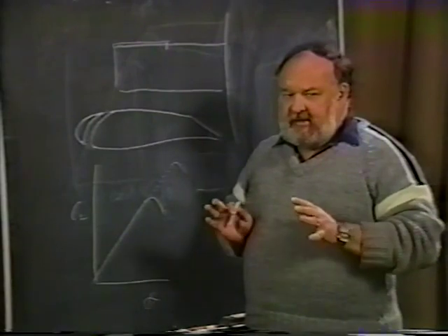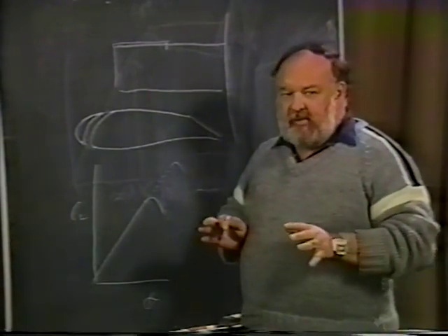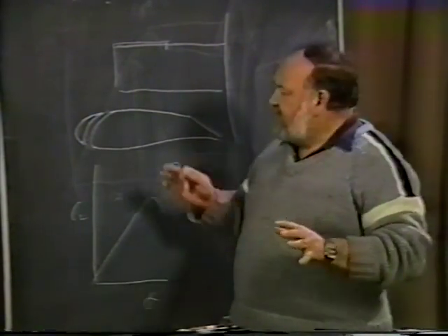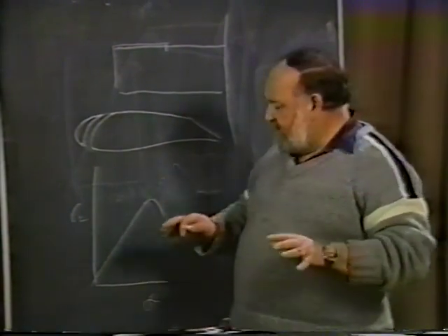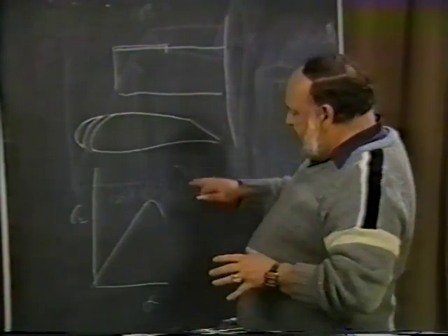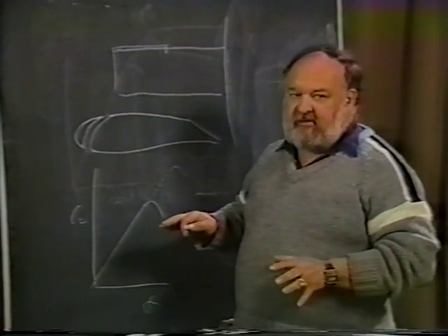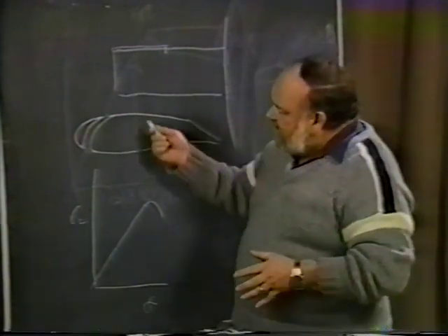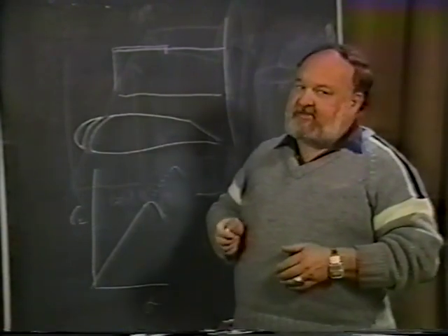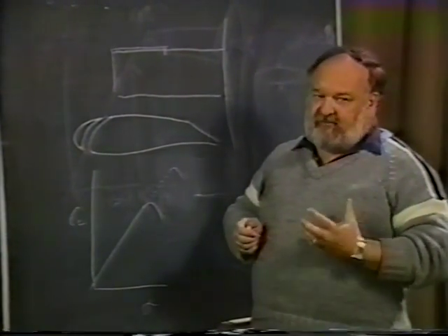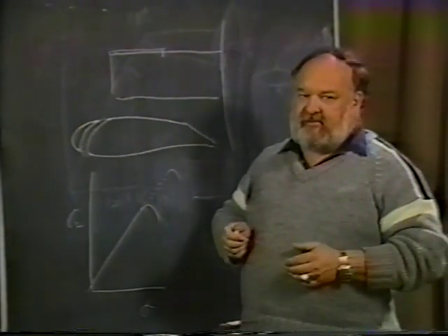Now that's an excessive amount in one way, but excellent from the standpoint of aileron control and stall control, because this slot allowing the wing to go to much, much higher angles of attack before it separates is extremely good. The problem with the fixed slot is that it just about doubles the drag of that airfoil section. It's a very significant increase in drag.